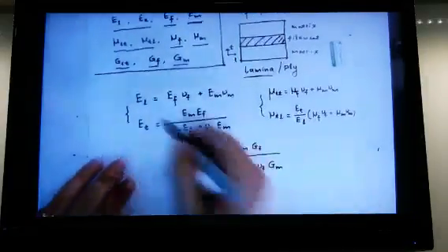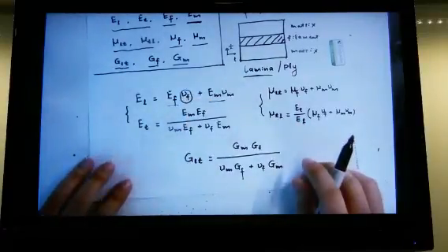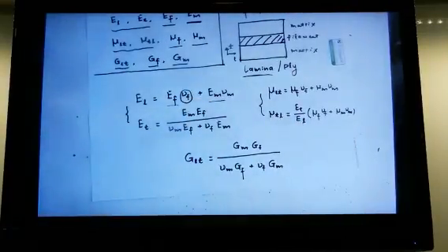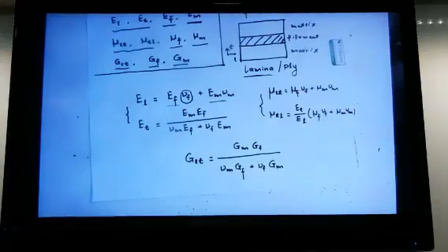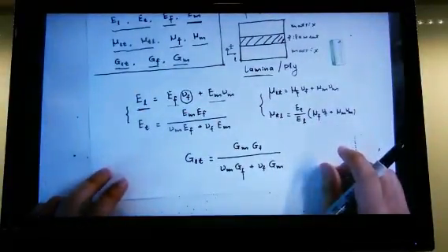So when you have fiber, matrix, and you have volume ratio, meaning volume fraction, because you put two materials together, you must be able to calculate what is the volume fraction of that material in the composite system. So this VF and VM are the volume fractions of the fiber and matrix. And when you have volume fraction, you can calculate the modulus of the composites.